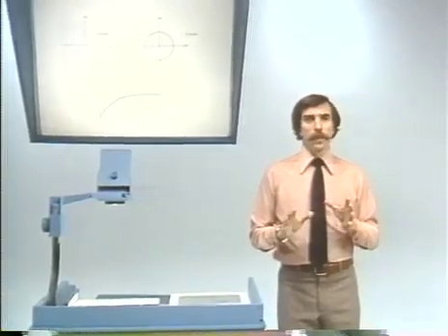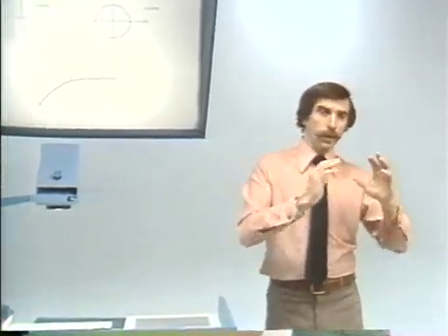Now, notice in this that there's no issue of aliasing. What's happened is that we've replaced s by a function of z, and it corresponds to mapping the s-plane to the z-plane. In fact, the whole j omega axis has mapped to once around the unit circle, which obviously requires some type of nonlinear mapping because, look, the j omega axis is infinitely long. The unit circle has a finite radius.